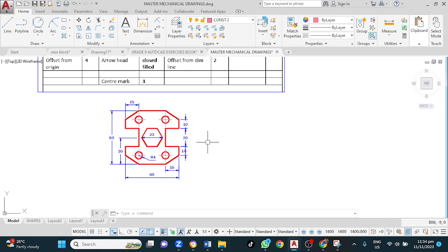In this series where I focus on AutoCAD 2D exercises, the tip for this video is: remember, always read the command bar before, during, and after. And always draw in the model space, using 1:1. You scale when you finish drawing. Do not set your scale before. Again, always draw in the model space using 1:1.